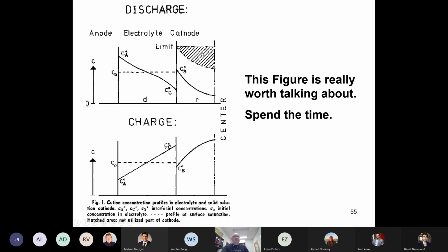So we don't do a CV step in discharge, but we do it in charge. So in charge, it means we try to empty the intercalation electrode completely in the CV step. If you really want to empty it completely, you would make the CCCV limiting current not C over 20, but something like C over 100. It wouldn't add that much more time because those currents relax pretty fast towards 0.